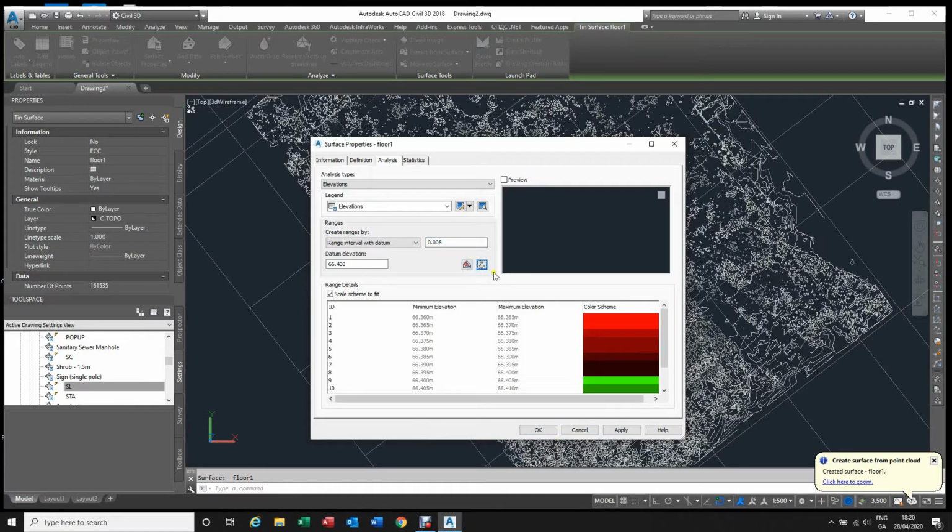Alright, and you see that this surface has some really low points and some high. This is not too bad, 25 mil above, but 35, that's a bit lower. Probably this is some noise I couldn't spot. I missed it when I was cleaning the point cloud, there could be just maybe 1 or 2 points on the point cloud. So what we can do here, I would like this area, which is the closest to the design elevation, have the brightest.